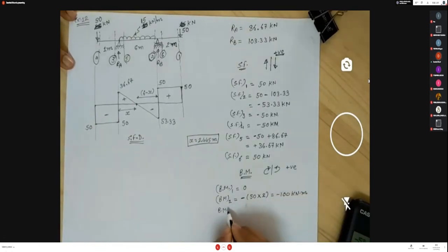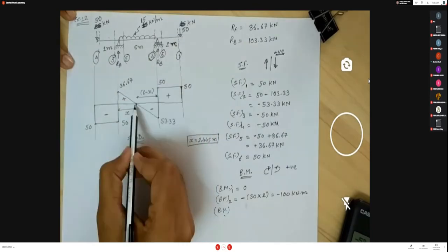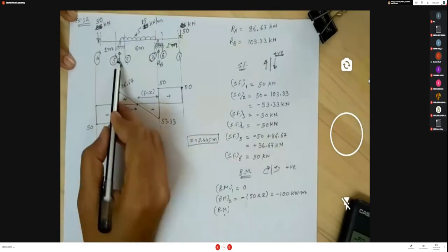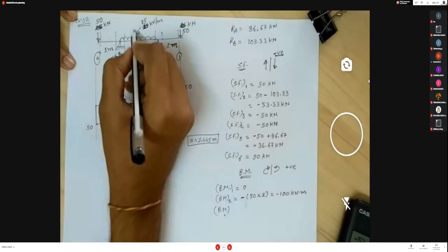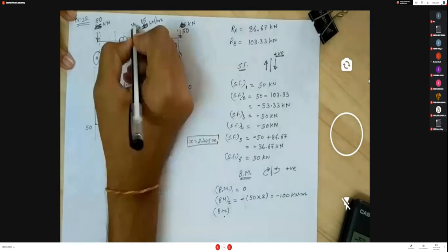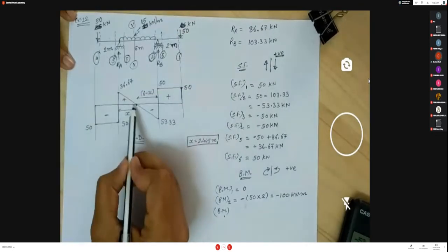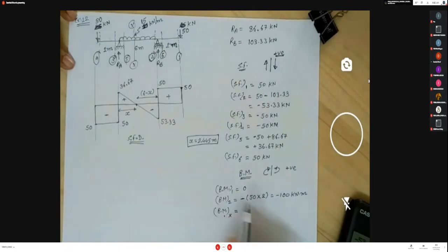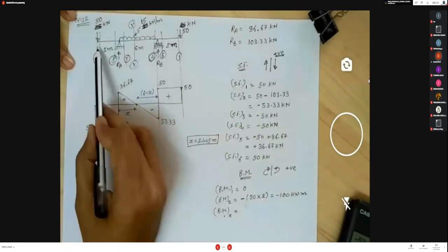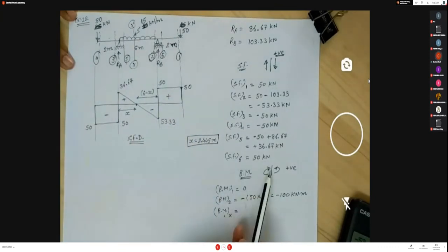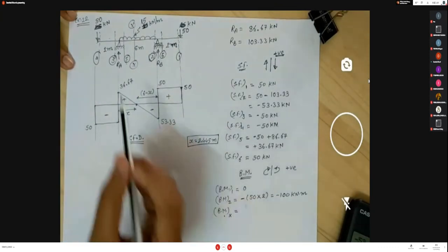Now the bending moment at the section which is 2.445 meter from point A. Say that this is section XX. Here our shear force becomes 0. So bending moment at X. Consider the left hand side or right hand side, and you have to apply the sign convention accordingly.